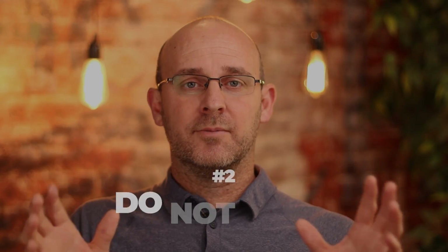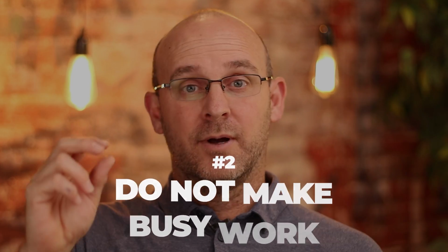Number 2, do not make busy work. That ties into number 1, but busyness is waste. So sometimes owners reps will say, oh my gosh, why is your team not doing this? Why is somebody not working in that zone? Why are you guys not working overtime? Why are you not working on the weekends? I want to see busy, busy, busy. Why are there not 30 more people out here? Busyness is waste. You could add 10 more people to every trade on the project site and not go any faster if the work isn't made ready. So instead of making the contractor or the teams busy, let's focus on clearing the road and making work ready.